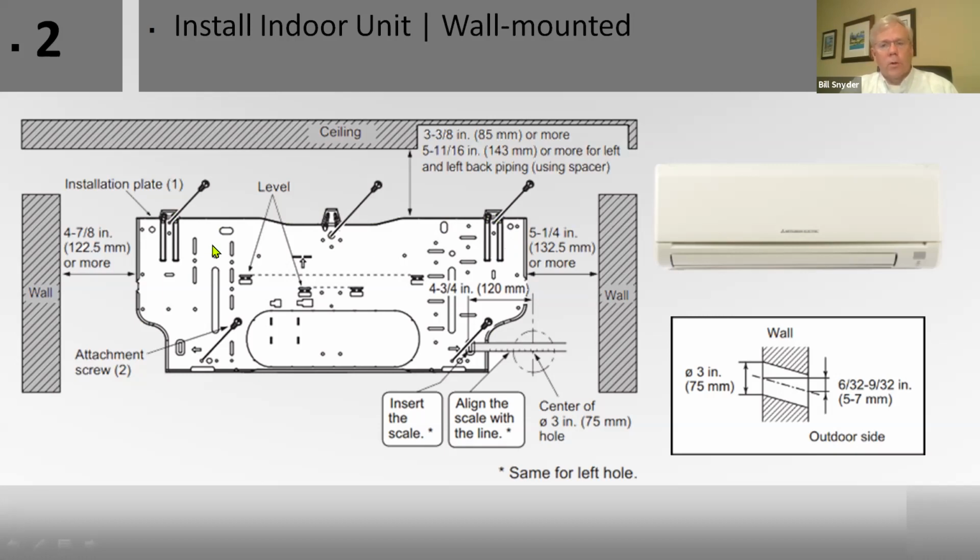So if it's going to bow like that, if you tighten this down and this side's sitting at half an inch, 3/4 of an inch from the wall, and you have to push it in place, loosen this up and put shims under either side so that it does not bow. Otherwise, you could get some ticking sounds, and then, of course, that will wake somebody up and you'll get a phone call. But on here, there are some little slots that kind of stick out a little ways.